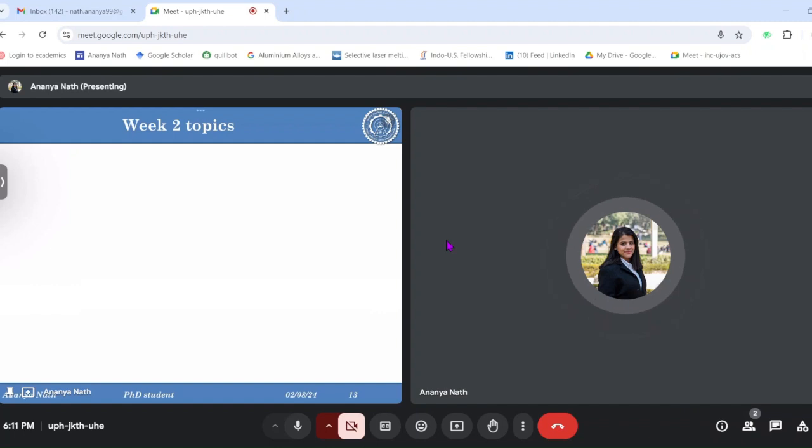Also, you can minimize the support by modifying the slicing. Slicing is again dealing with the solid body, unlike triangulation, because triangulation is done on the surface. In slicing, we slice the object into layer thickness. Slicing is equal to layer thickness.